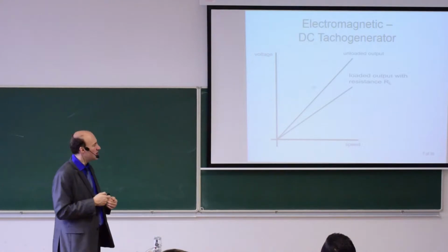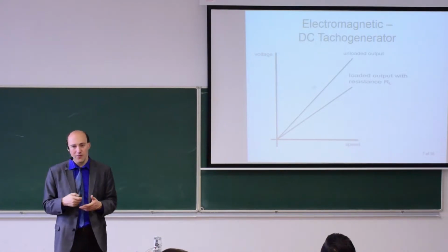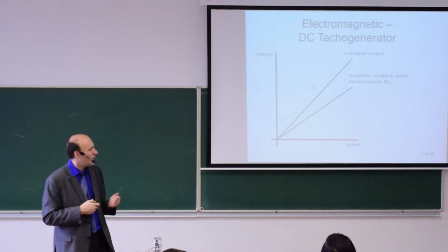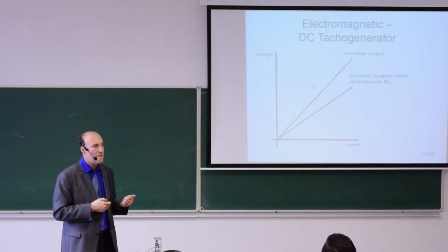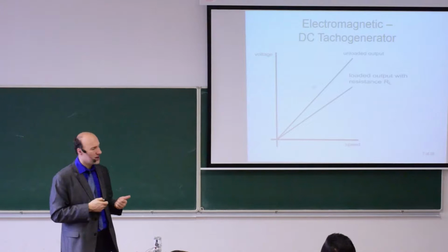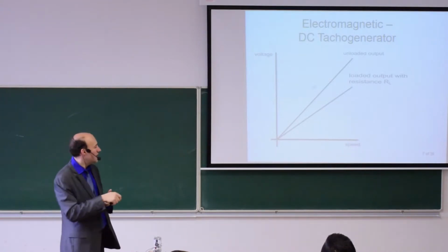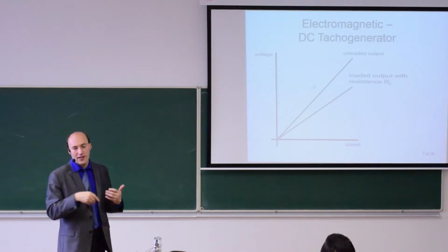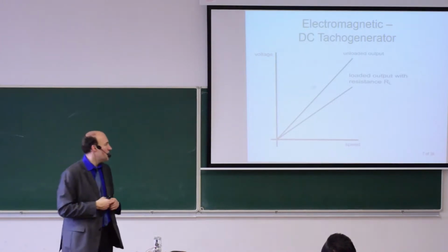So for this reason, if you look in some tables for tachogenerators, always look what is the minimal recommended load resistance, and you have to keep it, because then you will have the correct characteristic and not some smaller voltage that you actually measure.